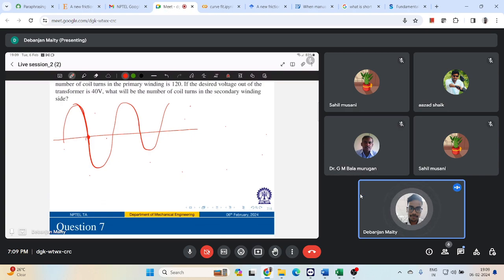The stability is very poor over there, the arc stability. So there is the need for reignition. So we have to reignite the arc, right? That requires a sufficiently high OCV. So this requires a high open circuit voltage, almost nearly 50 volt.